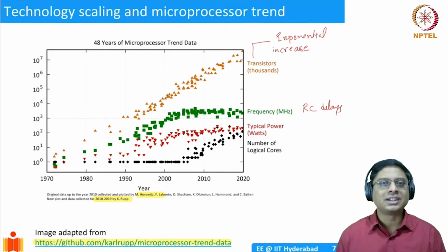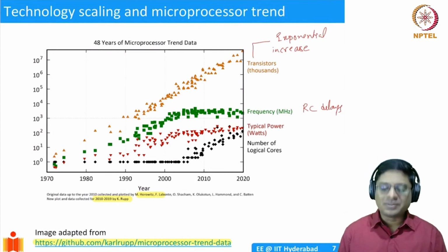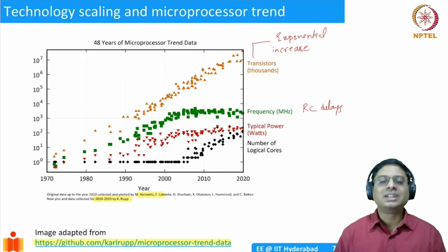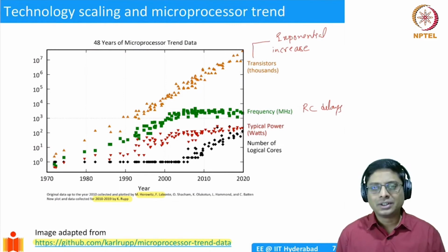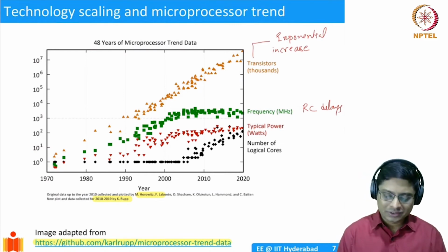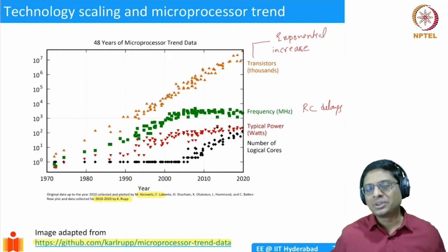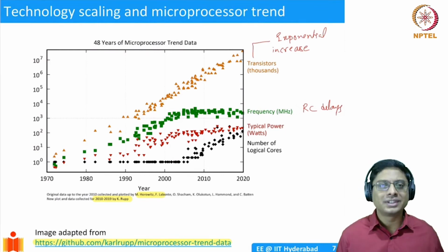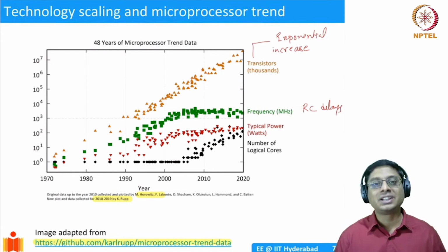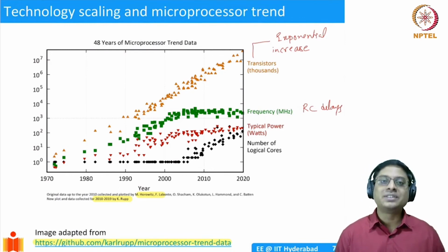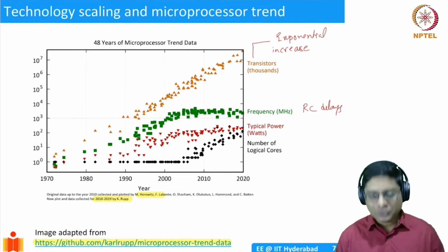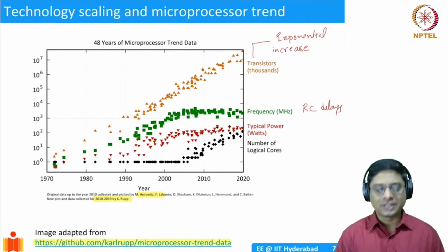Ideally, we want to do it instantaneously, but the current limitations of the technology don't permit it. So we are not able to go beyond this frequency. I mean, we can do it at a single transistor level, sure. But once you integrate, let's say, 1,000 transistors, it's very, very difficult to achieve very high switching speeds, especially with silicon. Okay, there are other alternatives, but with silicon it is not that easy to increase the frequency more than this few gigahertz.